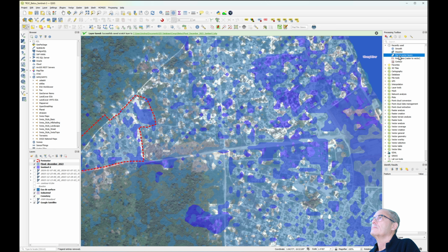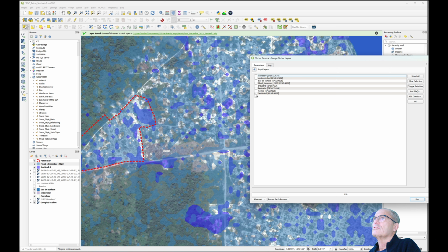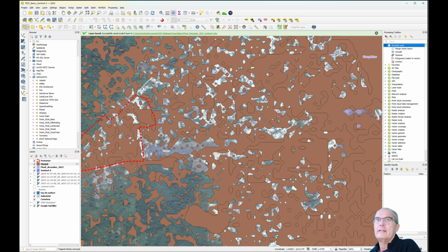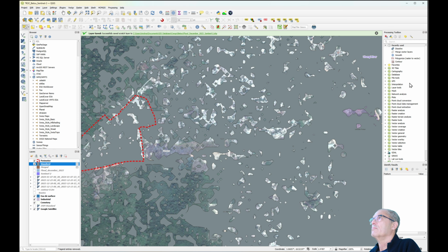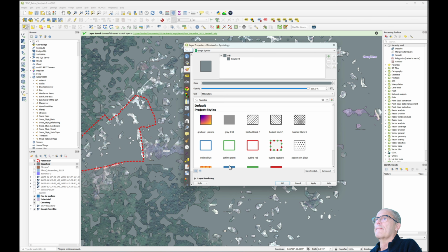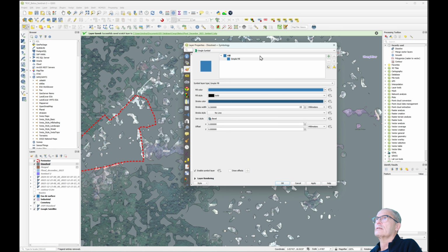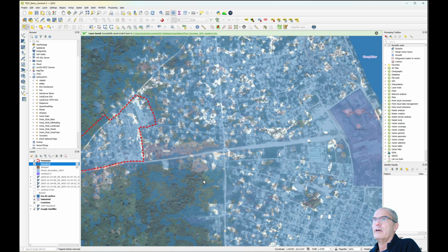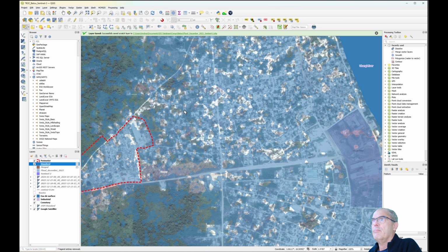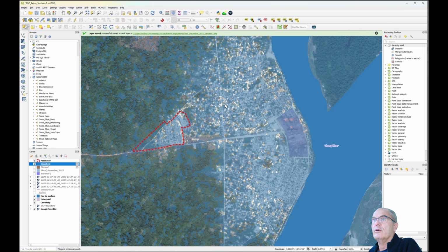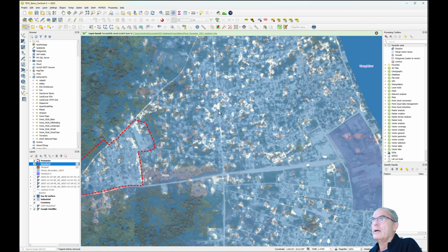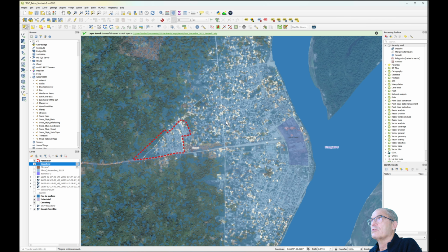Merge. We choose Sentinel-2 together with the flood of Sentinel-1. Here it is, same process. Now we dissolve those, okay, and we make it nice looking as well. Now line and transparent. At this point we have our flooding map based on Sentinel-1 and Sentinel-2 together in the day of December. You see, a big part of the city was flooded.